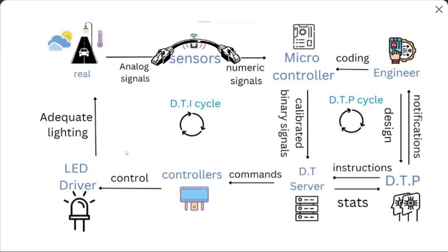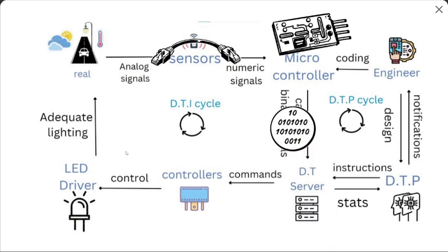The signals are then transmitted to a microcontroller, which processes the data, applies calibration factors and produces an output signal that can take the form of a binary signal or a more complex digital signal, depending on the type of data being measured. The calibration is mostly prepared in the lab beforehand and can be modified easily during maintenance time.